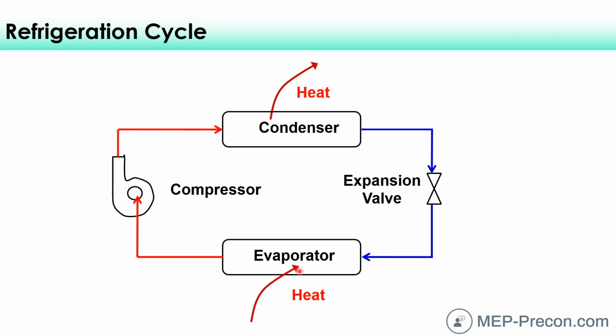And that's what keeps your car cool, because you're burning gas, you've got flames within your engine all the time. You've got to keep that cool, so we circulate water in your engine. And as air blows through that radiator, it removes the heat off the water that way. There's heat transfer that takes place within the fins. This works very similarly within what we'll call a packaged air conditioning unit.